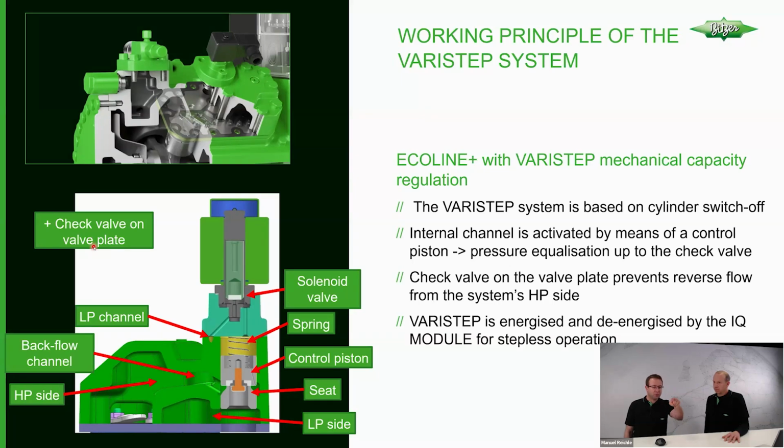Secondly, because we run it in this internal loop, there's not really a big mass flow. So in a lot of cases, the valves will maybe not move really. When it's unloaded, and this is also important for the efficiency later on, it's really only the mechanical wear of the drive. There's not really compression work done either.